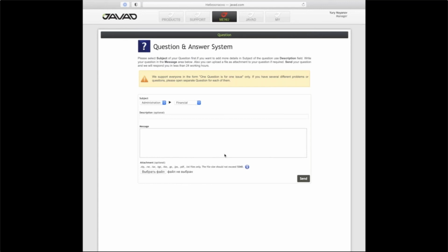GMT stores both data from the base stations in WGS84 and the original coordinate system, for example, NAD 83. And for each point, you can switch the coordinates in the pane to see the coordinates either in the original coordinate system transmitted from the RTK base or in the WGS84 coordinate system converted by GMT.